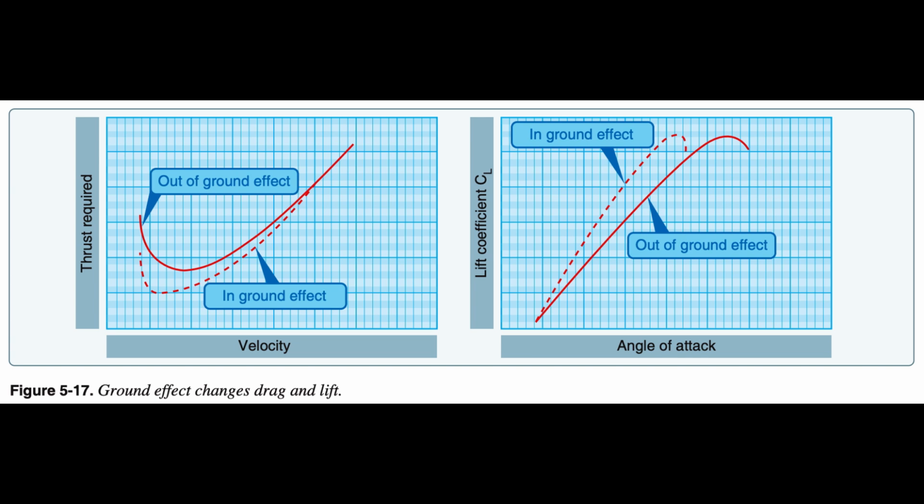of airspeed during takeoff may permit the aircraft to become airborne but be incapable of sustaining flight out of ground effect. In this case, the aircraft may become airborne initially with a deficiency of speed and then settle back to the runway. A pilot should not attempt to force an aircraft to become airborne with a deficiency of speed. The manufacturer's recommended takeoff speed is necessary to provide adequate initial climb performance.